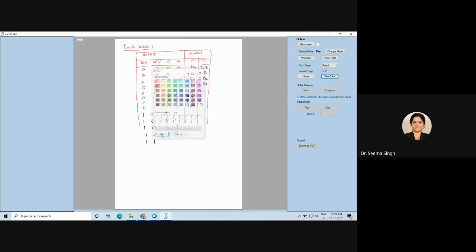I hope you people are understanding what I am doing. 1Y will be 0, ma'am. 4 zeros. 1Y will be 0 because your first mux is not getting selected, because the first enable is a 1. So the first mux will be 0 this time, and your second mux will have its data, because the second mux is enabled by having a 0 here, because I told you that your second enable is active low. So we are done with our third category of the input when you have 1 0.